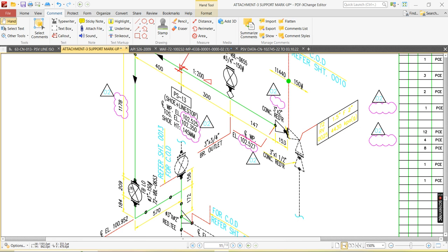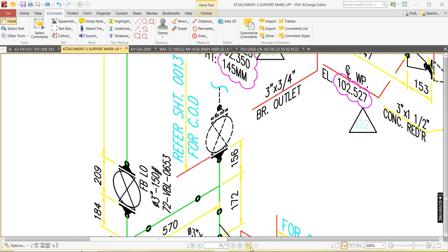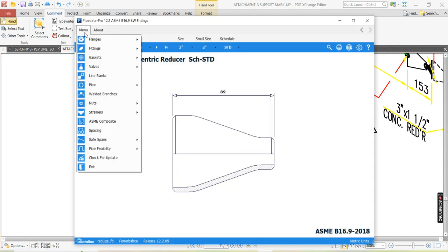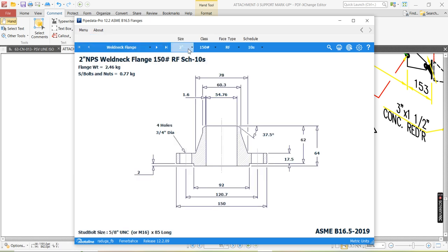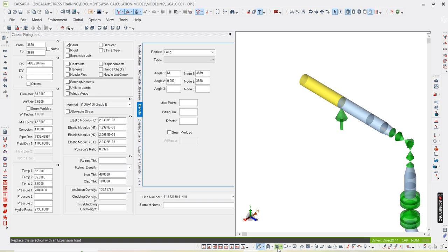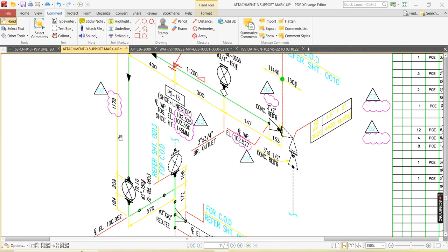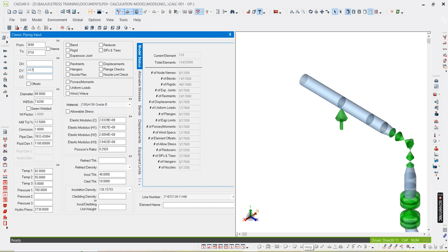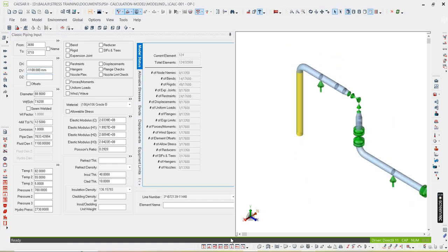You see, so I have to check the flange. 150 rating only. 3 inch 150 rating flange. Flanges 16.5, 3 inch 150 rating. The dimension is 70 mm. Okay. So the line is dropping 1178. It is going in negative y direction. Minus 1178 plus the flange dimension is 70. I am subtracting that one. The line is getting dropped.